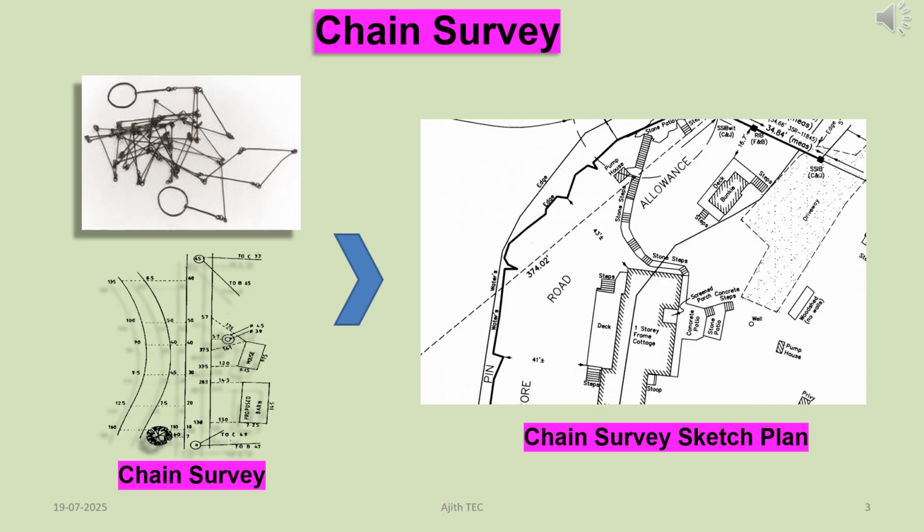This slide shows how to perform chain surveying with required instruments. Collecting required measurement of details using chainage and offset method, and prepare chain survey sketch plan for given land parcel.